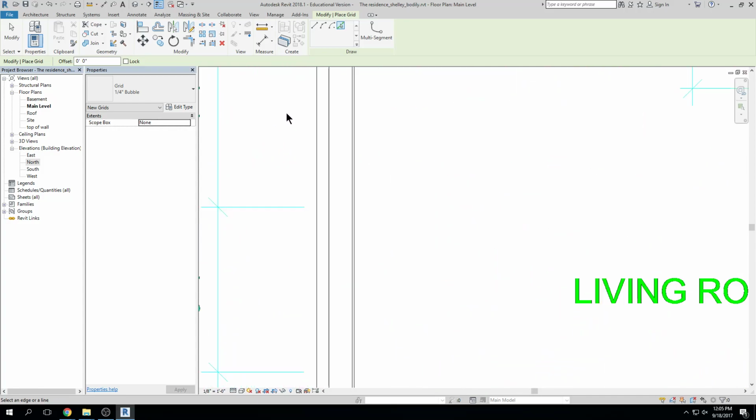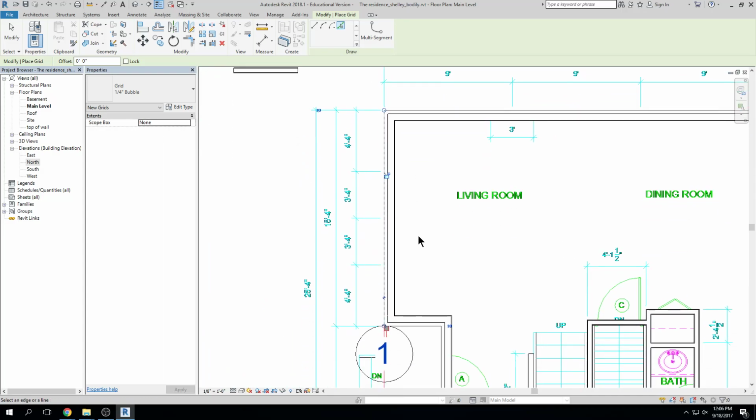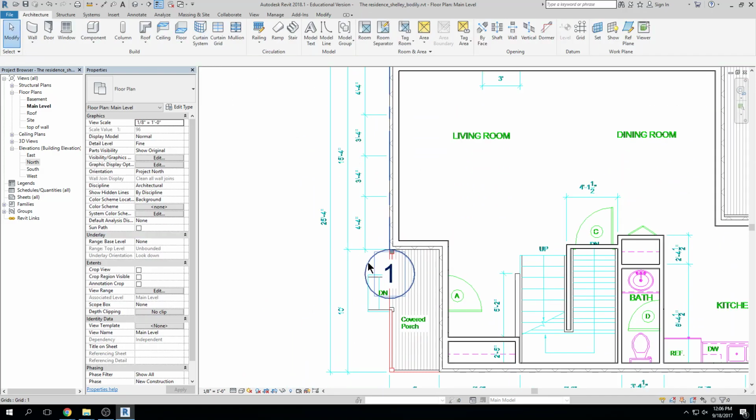So I come back into my project, I click on the outside of my wall, you see it highlights, click. Now I can immediately lock that element to the outside of my wall, which means if the wall moves, the grid moves with it, right? Which makes sense. Or if the wall moves, you get an error that says, hey, the grid that is locked to that wall is moving. Did you really want to do that? Are you sure? So that if a structural element is going to be moved, at least you get an indication of that before it actually happens, okay? I'm not going to lock it just yet because we're going to be manipulating these. But essentially what happens is, let me hit escape.